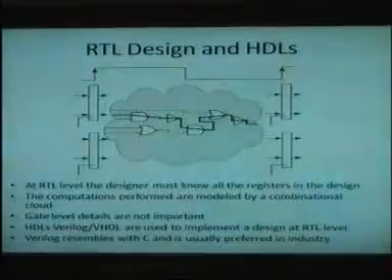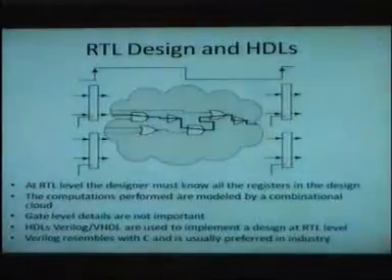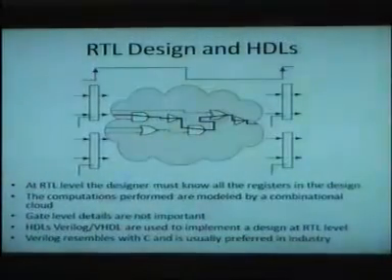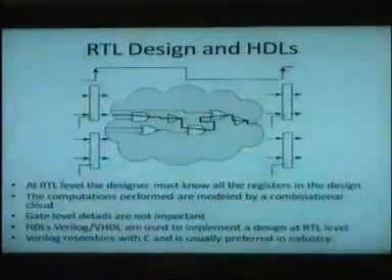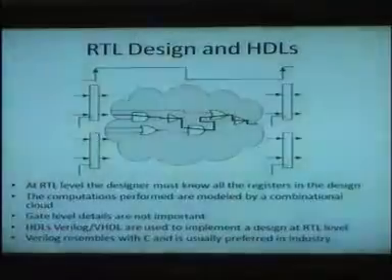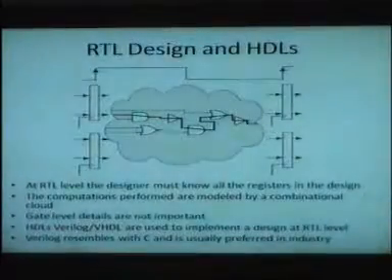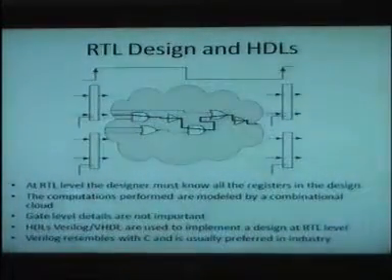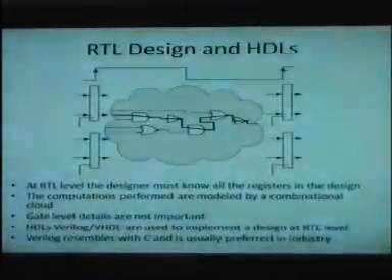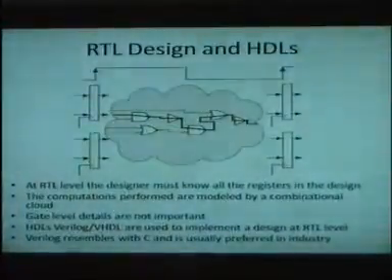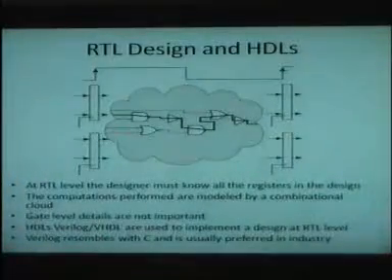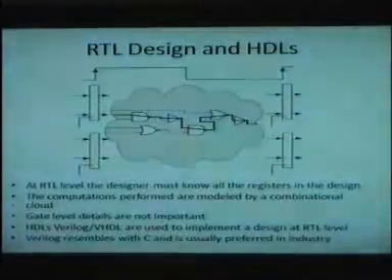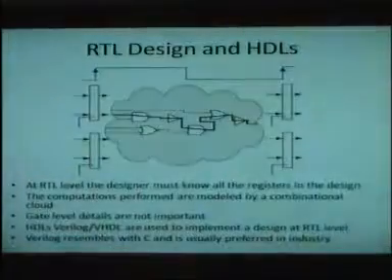Now you have 2 options. One is that you change your design. The other is you start putting registers in between, because from posedge clock to posedge clock you have a register to register delay. I will study how you insert registers in between. It's very cumbersome if you have not thought of it at the start of your design. Putting registers in between is a very, very challenging problem.